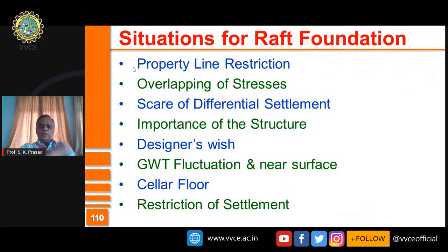Well, when you cannot go for combined footing, you will look for strip footing. Even when it is not possible, you go for raft foundation. I say raft is a complete shallow foundation. It's going to eliminate majority of the problems. Given a choice, you should go for raft foundation, which also enhances the stability of the foundation. Of course, it is more expensive than isolated footing, combined footing, and so on. But it will solve many of the problems.